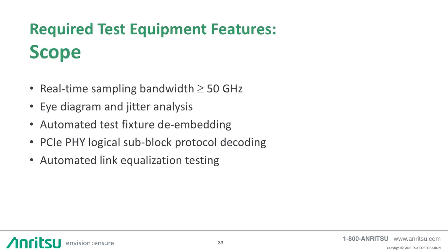As we've seen, the PCIe 5.0 physical layer tests require an advanced bit error rate tester and an oscilloscope, both capable of emulating the PHY layer behavior of the SerDes. The minimum requirements for the oscilloscope are listed here. It's a wide bandwidth scope that can operate standard serial data analysis software and also has the ability to run PCI SIG test software analysis tools.